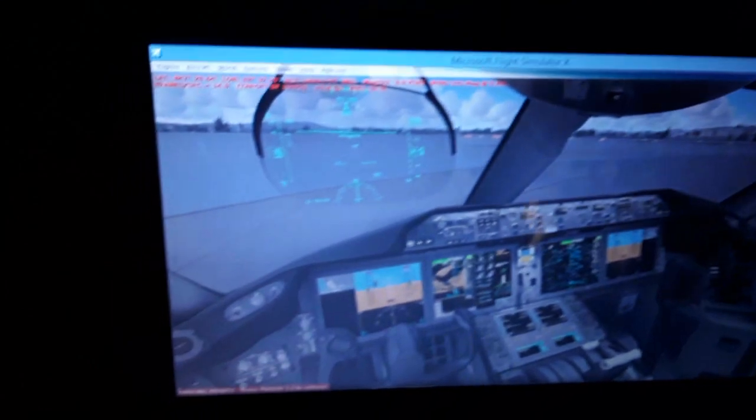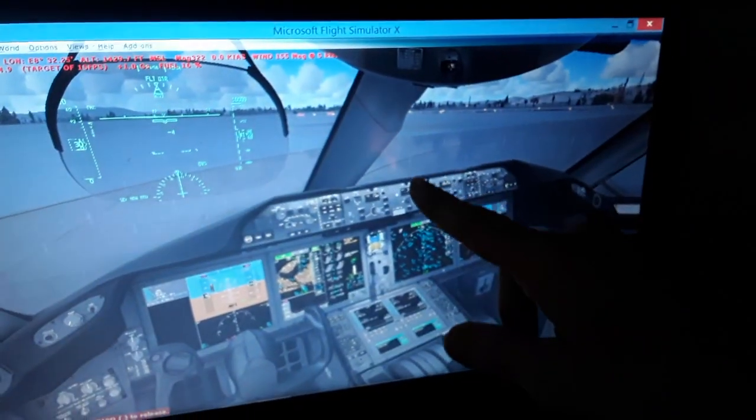Also, we have the altitude indicator with the artificial horizon. You can see the LSZH localizer. We have the horizontal localizer and the vertical glide slope that we receive. We have the radio frequency antennas at the runway thresholds that transmit for takeoff and for landing a radio frequency unique to each frequency tune setting we made, and also the magnetic north heading of the runway we have set in the autopilot flight director system panel.